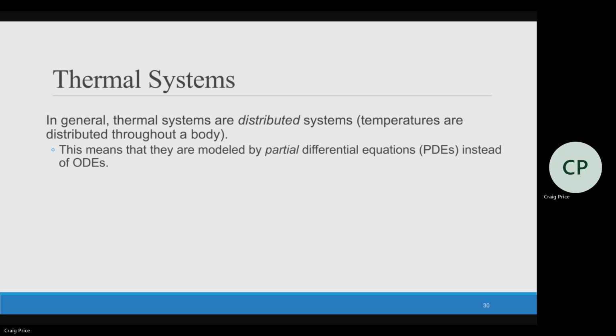In general, a lot of real systems are nonlinear and distributed. When I think about temperature, think about the wall right there. Is that wall all the same temperature throughout? Even if I'm looking at just the exterior part of the wall, it might not all be exactly the same temperature. Why is that? Some parts of the wall might be more filled than others, so there's a slightly different capacitance at different points along the wall, and so I have a lot of different temperatures.